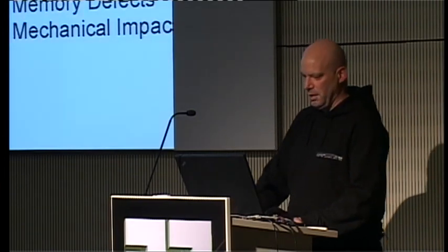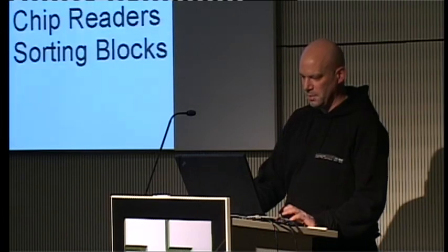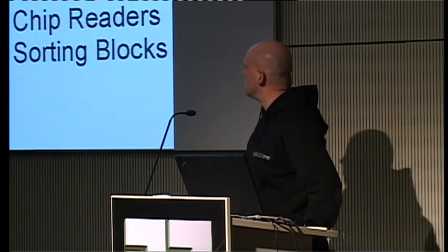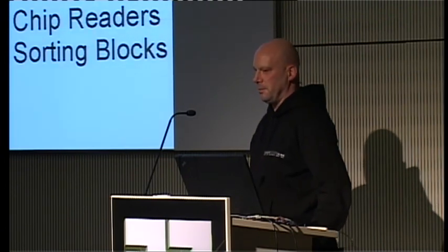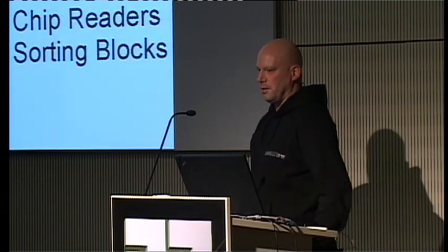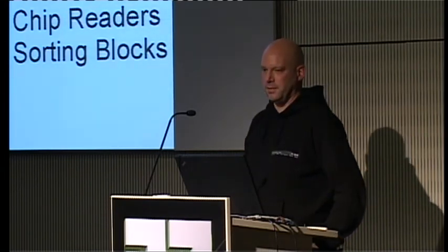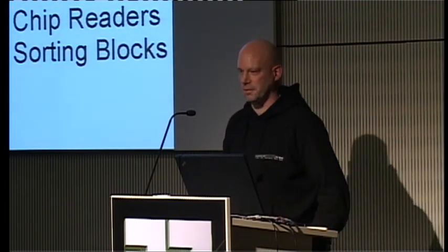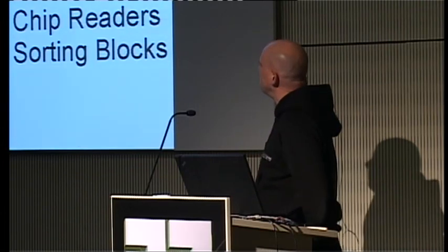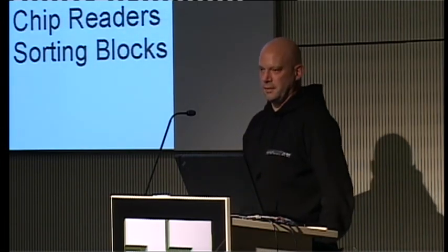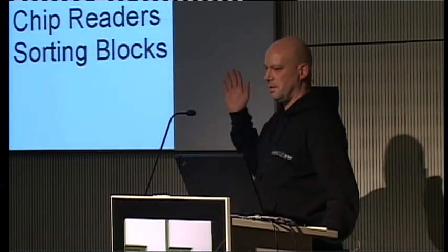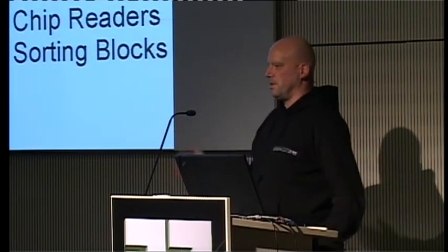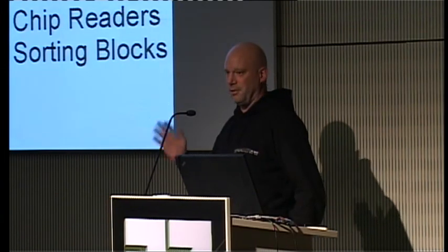Good. Now, I think I skipped the flash, sorry. Well, the easiest damage is a PCB or circuitry damage, and that, of course, can be repaired to get the data out. But I can tell you from my experience that it doesn't happen very often. If that doesn't give you the data back, then you have to desolder the chips. Then you have to read them, and then the adventure of bringing the blocks back into their original order begins.